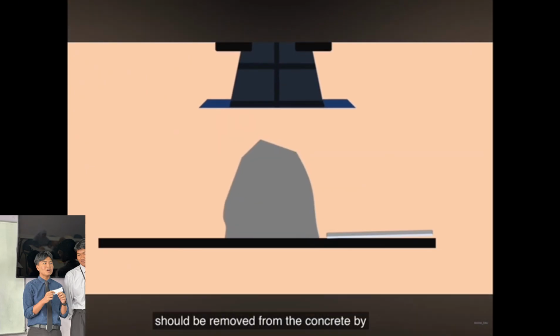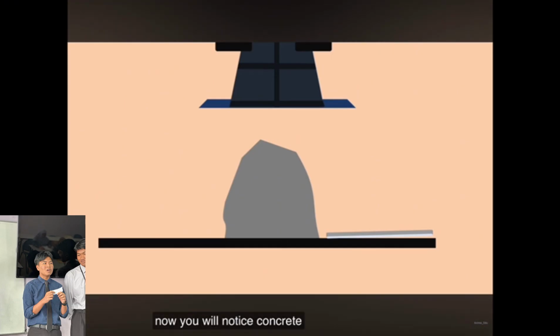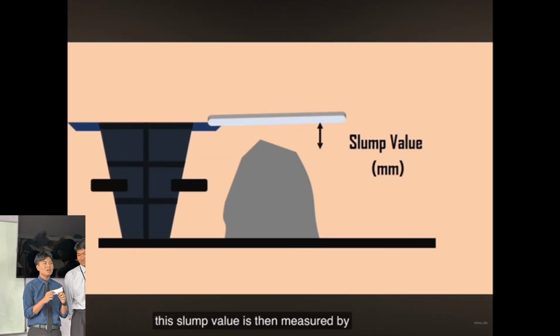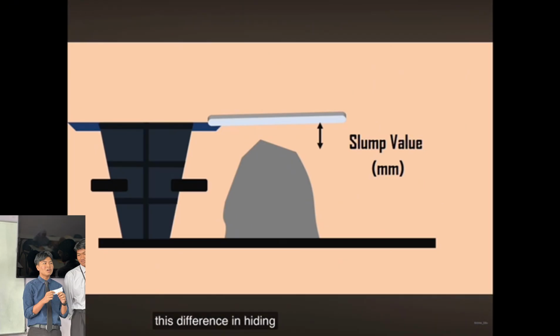The mold should be removed from the concrete by slowly raising it in the vertical direction. Now you will notice the concrete tends to subside. This subsidence is referred to as the slump of concrete. This slump value is then measured by the difference between the height of the mold and the height of the highest point of the specimen. This difference in height is taken as the slump of concrete.